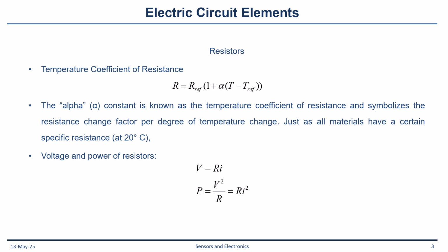And normally resistors also change with the change of temperature. So in the previous example the R was 2.6. Normally the resistance value that you can find is for a temperature of 20 degrees. So if we change the temperature, for example to a higher temperature, then the resistance will change and go higher. So Tref normally is 20 degrees Celsius, and T is the new value.